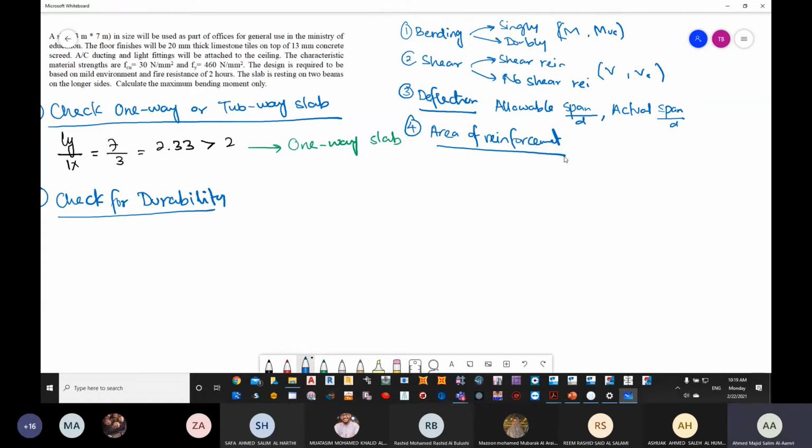The elements you are designing are using a concept of under reinforced or over reinforced or a balanced section. Under reinforced. So if you are doing under reinforced, will you do something lesser than the required? Because if you are saying lesser than the required, then your element will fail.